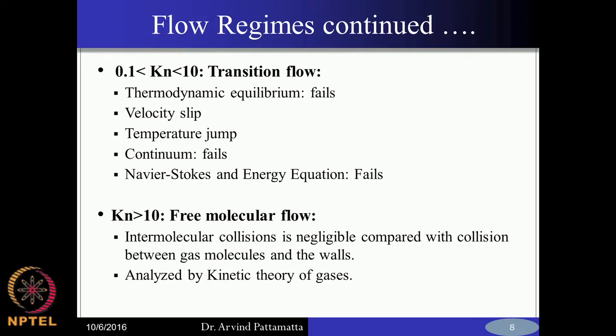And then how do we analyze this? Even the Burnett equations cannot be applicable here, so we have to resort to the Boltzmann transport equation again. For the real subcontinuum picture we use Boltzmann's transport equation, with the simplest assumption being the relaxation time assumption. Okay. So, in rarefied gas dynamics, the BTE with the relaxation time approximation is used when you are in this particular regime, Knudsen number greater than 10.